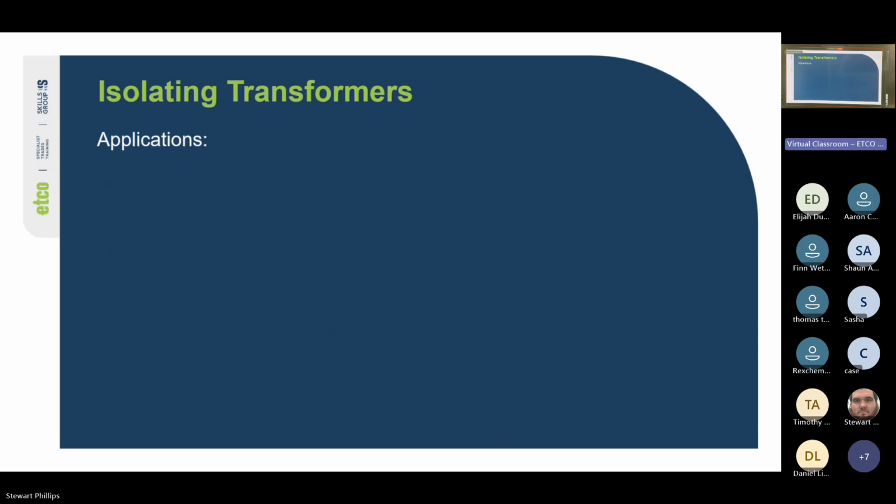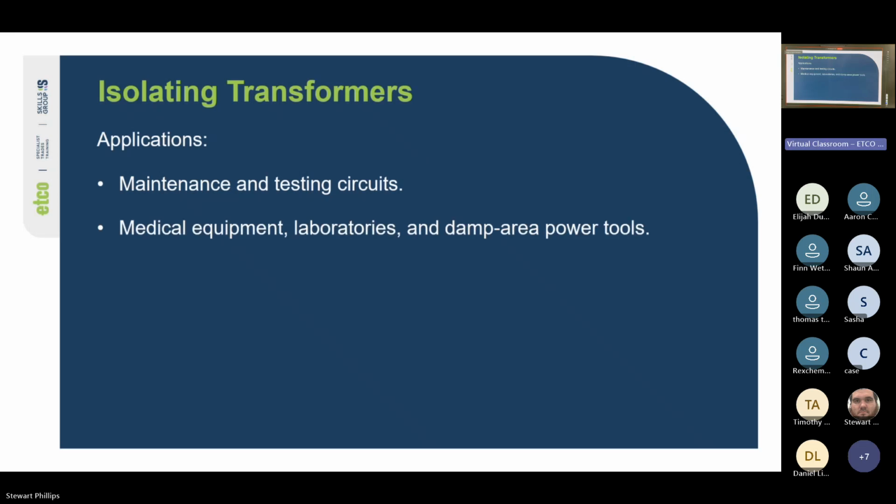Cool. So some applications for our isolating transformer. So maintenance and testing circuits. Sometimes we need to have a separate earth for maintenance and testing purposes. Cool. So medical equipment, laboratories, and damp area power tools.